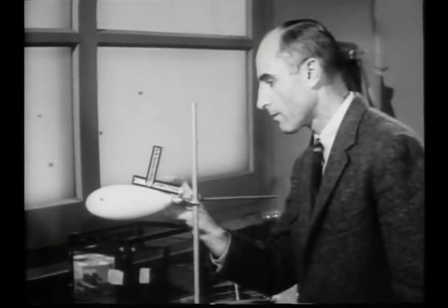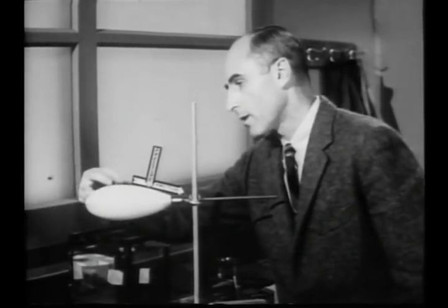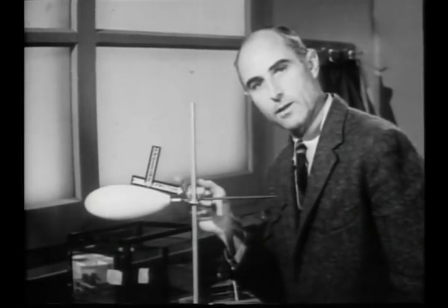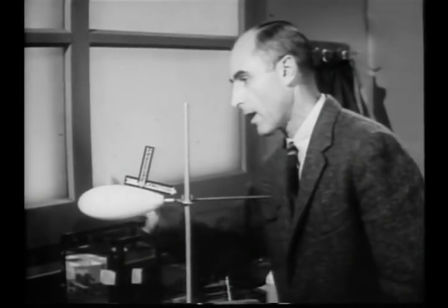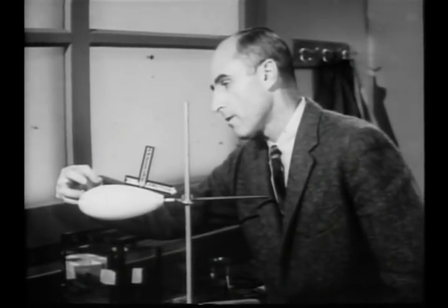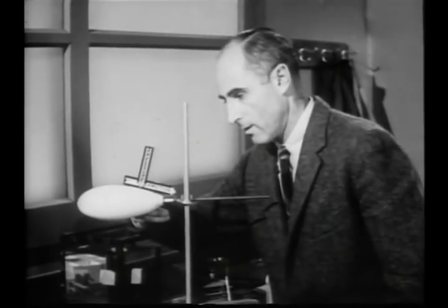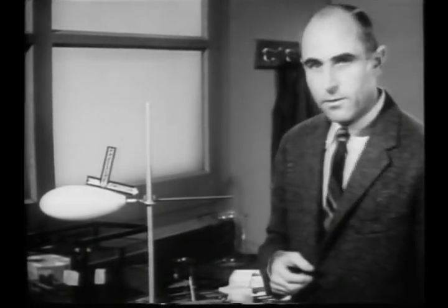If the average pressure on the rear half is equal to the average pressure on the front half, then the net pressure drag is zero. But if the average pressure on the rear half is much less than the average pressure on the front half, then there is a large net pressure drag. The reason for thinking separately about these two types of drag is that they arise for different reasons, and since one or the other may predominate in different ranges of Reynolds number, it is not so surprising that there are different and distinct types of fluid behavior.